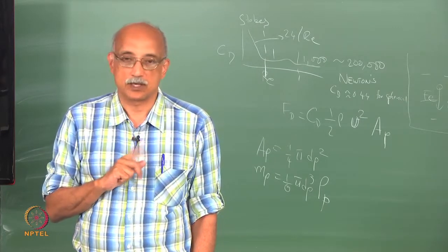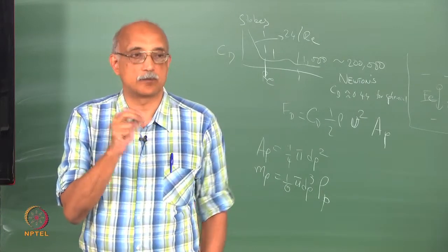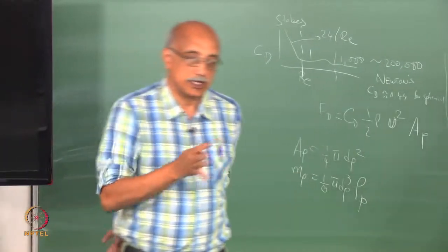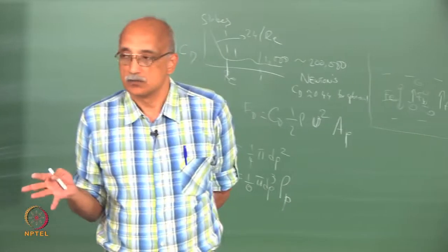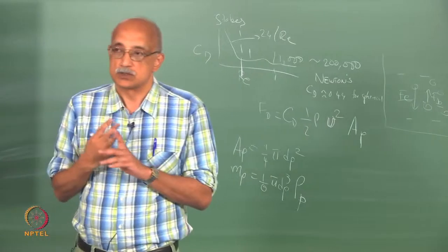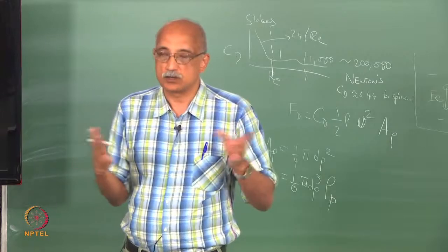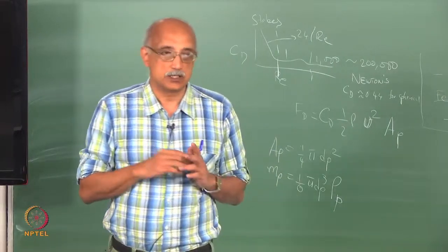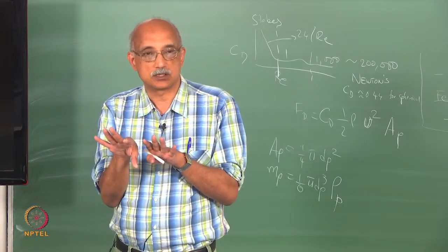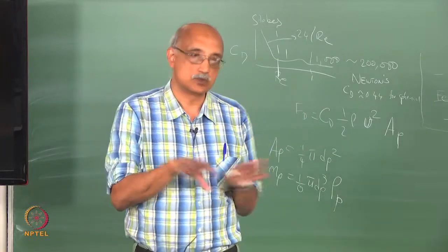It's actually based on the boundary layer effect. In the case of small particles, the thickness of the boundary layer compared to the size of the particle is significant. And when we talk about two neighboring particles affecting each other's motion, what we are really talking about is the interference between the boundary layers that surround them. So, the more prominent the boundary layer, the more prominent the effect of hindered settling. A large particle, by comparison, has a relatively small boundary layer, and therefore, two large particles that are separated by the same distance are likely to have less of an intrusive effect on each other compared to two small particles.